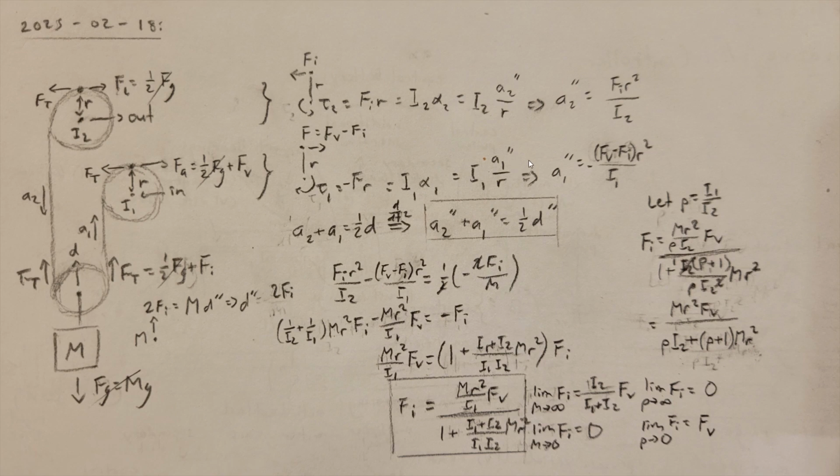The Huygens Drive is simply not a very good way to filter an input, and it is arguably being misapplied. The Huygens Drive was originally designed to have the input sprocket locked most of the time, while the tension from the mass drives a constant load of a clock escapement, the force disturbance from lifting the weight only happening every few days. Since the mass is allowed to fall, it is allowed to apply a constant force over a distance and hence do work. In your design, we try to keep the mass's position constant, so it does not move and thus cannot do any work toward maintaining the machine's speed.